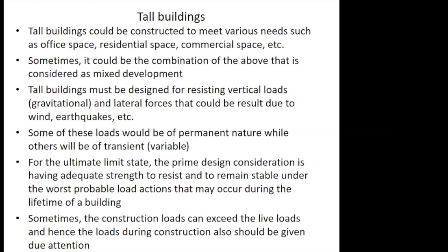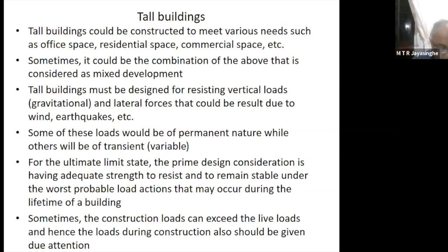But one of the very important things you have to keep in mind is, when you are dealing with tall buildings, any structure like transfer plates can be categorized as key elements. A key element is one where the failure can cause a significant collapse of the building.